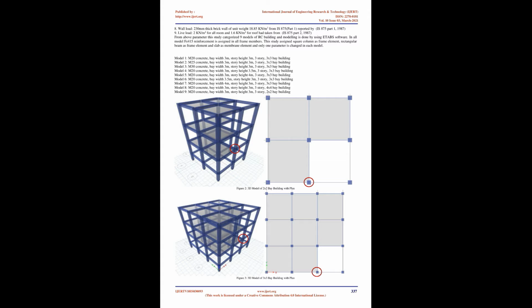Visible damage will be seen on the joint during inelastic deformation of beams and columns, and the effect of this force is known as plastic hinge. During inelastic rotation, the ductility capacity of all members is transferred to the joint, so the damage at the joint will be substantial and should be avoided. The formation of a plastic hinge is expected where permitted structural damage occurs. Thus, it is very important in seismic design that the damage of plastic hinges occurs in the beam, rather than in the column.